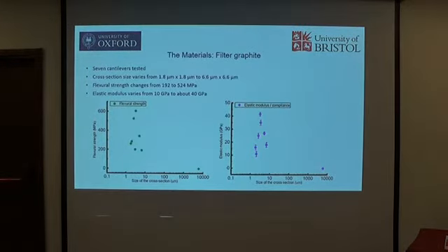In general, if I plot the data, the flexural strength I measured from the cantilevers are very high numbers, from 2000 to 600. And this is the number you usually get from a millimeter, centimeter or meter scale type of macro size sample. So here is the elastic modulus. It's again much higher at this small scale testing for these type of samples, which means that the micropores have a different mechanism of failure from the macro scale using those large samples.